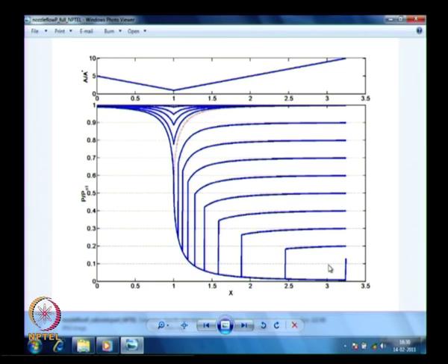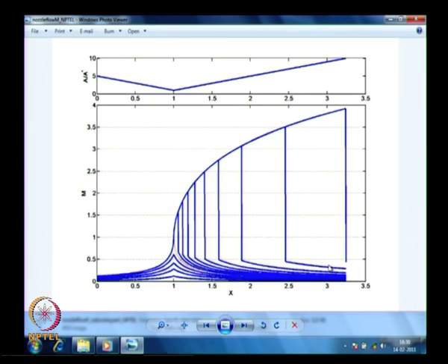Now, we will go to the next plot. We had this Mach number discussion anyway. This is the Mach number plot, okay. Now, whatever she was talking about is actually true, right. The strength of the shock is actually related to how subsonic can it take the flow, if you think about it that way. Actually, let us explain this again: the same nozzle plot above, A by A star versus distance along x axis, and here I am plotting Mach number at every location versus x axis, for the same set of Pb by P01 I used to plot in the previous case, okay.